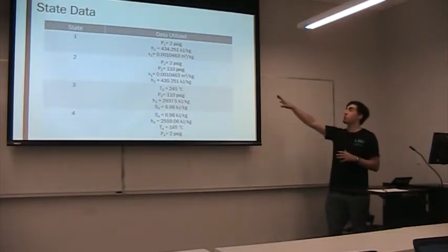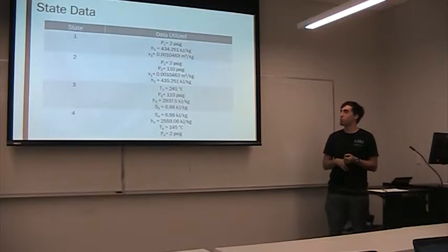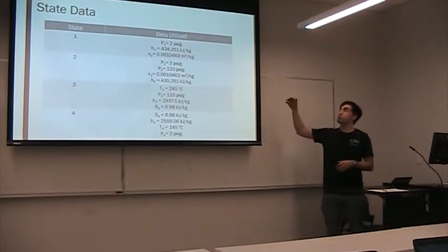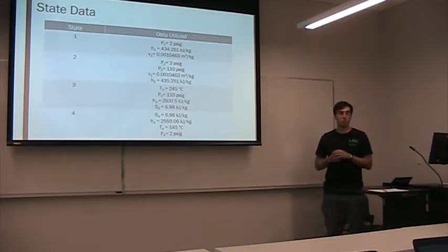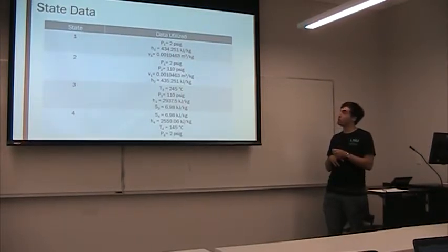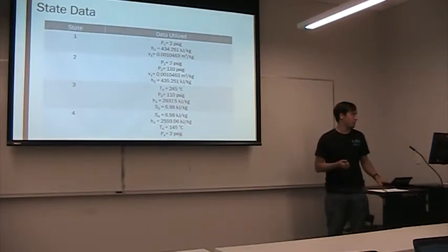So again, like I said, I used enthalpies, entropies, and specific volume for one portion of it, for the different states. As you can see, the pressures were just the ones recorded: 2 psig leaving the turbine, the boiler pressure, which is 135, 110, and the temperatures. It was really easy to just go along in the steam tables and figure out what the enthalpies were from that, to figure out the heat input in the boiler and the work out.